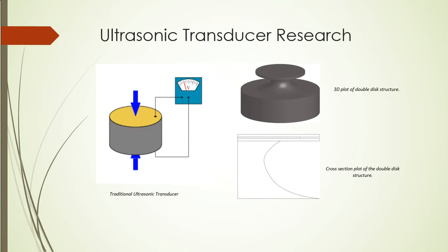In 2014, I worked with my teammates to conduct an optomechanical ultrasonic transducer research. In this project, we compared traditional ultrasonic transducers with optomechanical ones, with the advantages of optomechanical effect. Certain ultrasonic signal will change the displacement difference of the edge between two disks, resulting in an optical resonance shift, which will change the optical output. Using this principle, we realize the sensing of certain ultrasonic frequency.